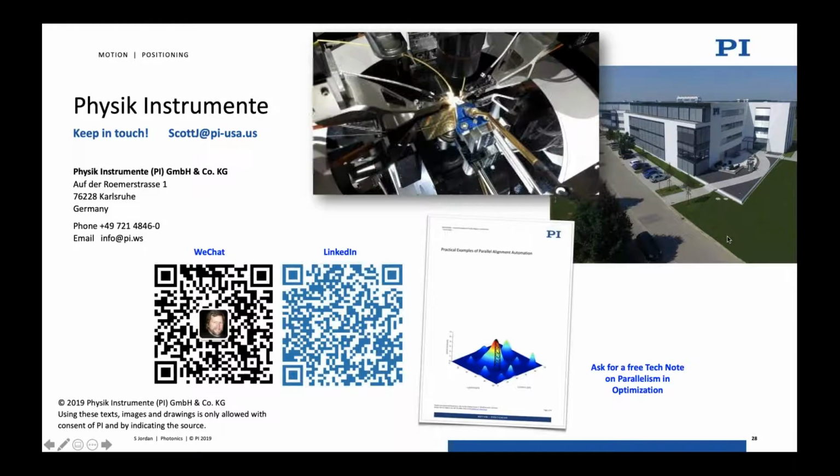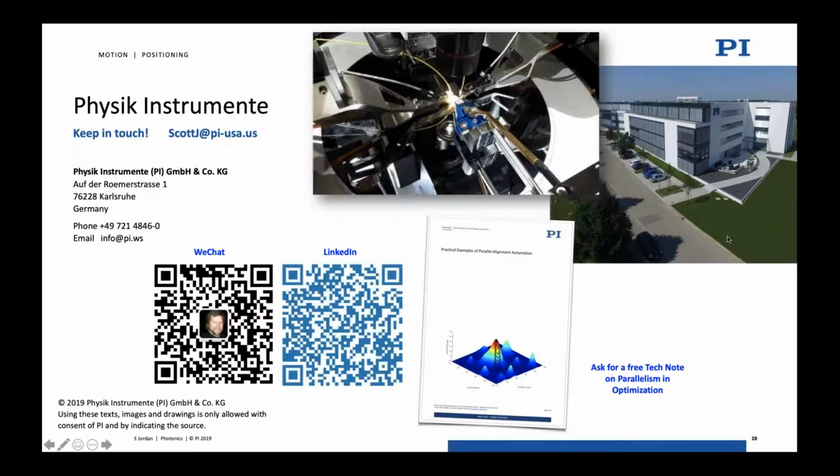Okay, the best way to explain it is to consider you have a positioning device that is precisely aligned to the optical axis. So when I rotate, I'm rotating about that optical axis. Now, achieving that with shims and maybe telling our hexapod exactly where to put things, you'll get close, but you will probably not get exactly on the optical axis. With this technology, you don't care, because we can lock on to that optical axis using the XY gradient search, which is very fast.